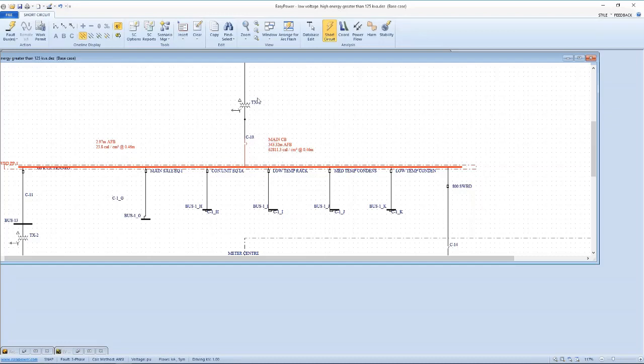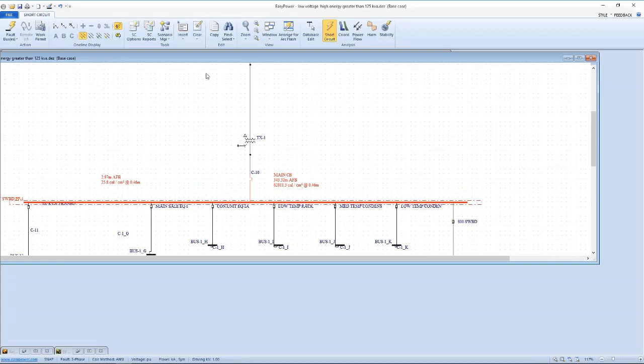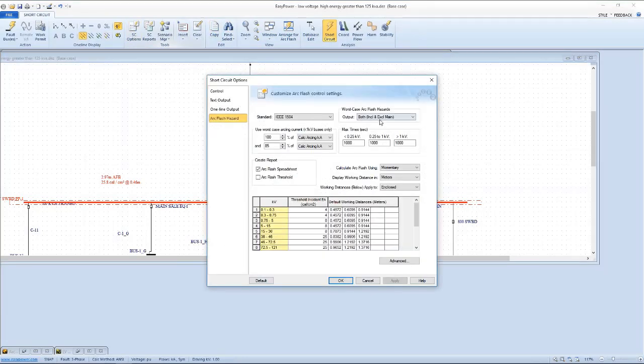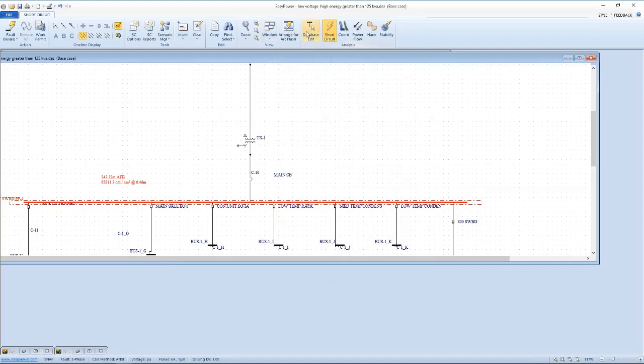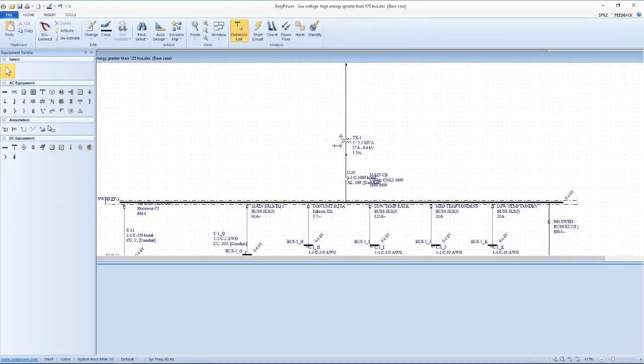The question was, if I have two different sources of energy, in this case a standby generator and a utility, and I get much higher incident energy from the standby generator because the currents are lower, how can I display that? What I would suggest, or what I did suggest in this particular case, is rather than trying to do my both sources thing, let's stay with my basic setting. On my one-line diagram, I insert a note with a leader that points out the area that I want to have extra information added.